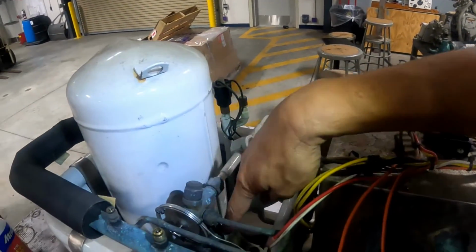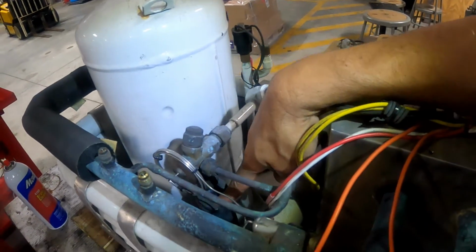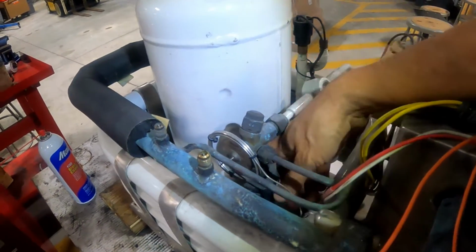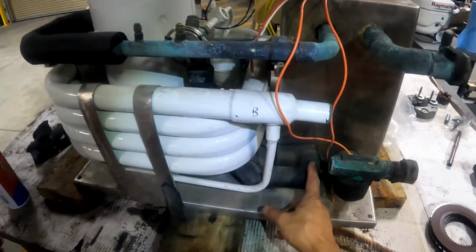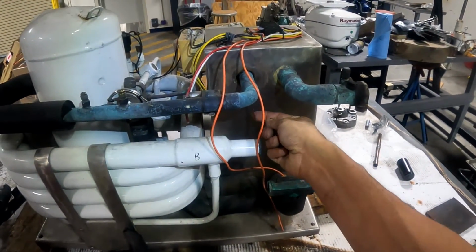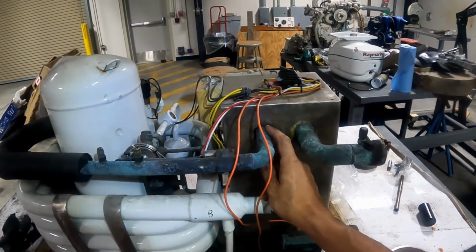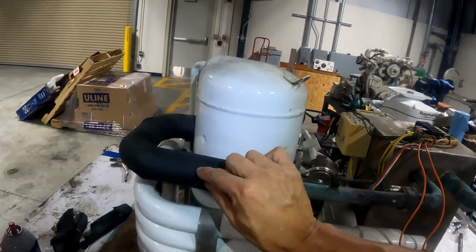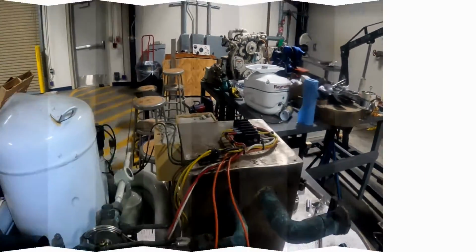When the expansion valve opens, the refrigerant goes to the bottom right now. The pressure and the temperature are reduced dramatically and freeze this pipe. This pipe is protected with insulation because it's frozen, and that frozen pipe enters the bottom and passes here and starts to evaporate the refrigerant. And right now here at this point the refrigerant is evaporated, but it's too cold, of course. It's evaporated and continues as vapor, and enters the compressor, and the cycle starts again and again.